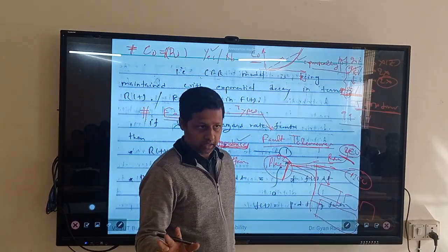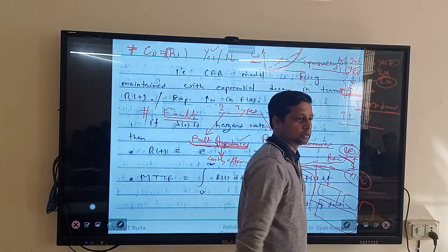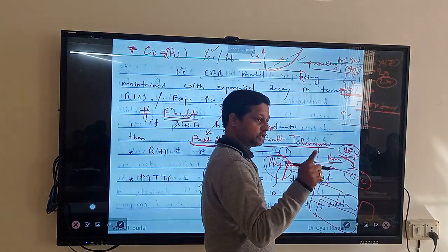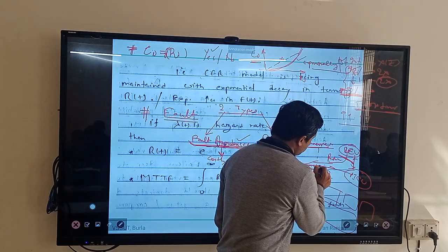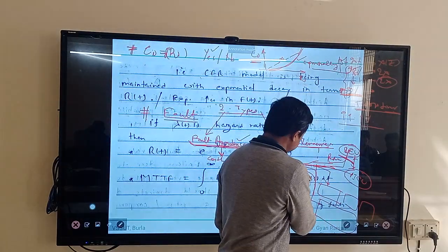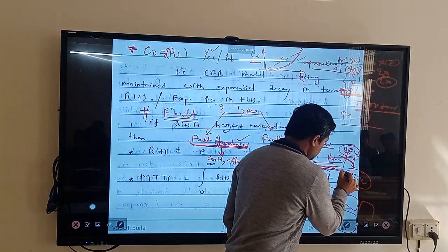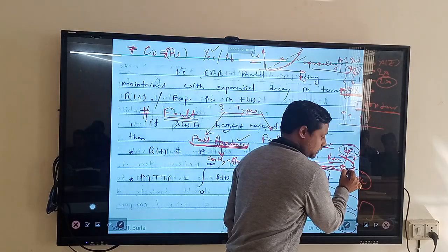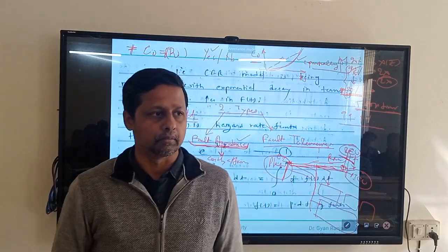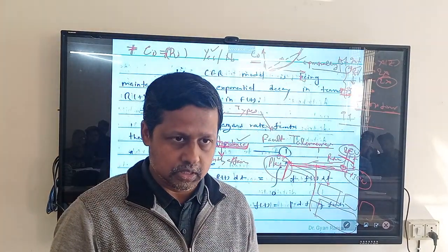Let's say this ICU is just next to the ICU unit. Getting my point? Okay? Now everything has a cost. Will you follow one line from the starting point, the processing plant, another line from here to here, or probably you will ensure another valve here and fix one line here, fix another line here. Which one is more preferable? Second one, no? Why? Installation cost is less.